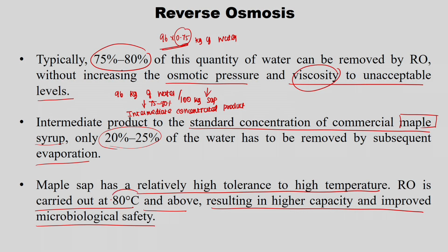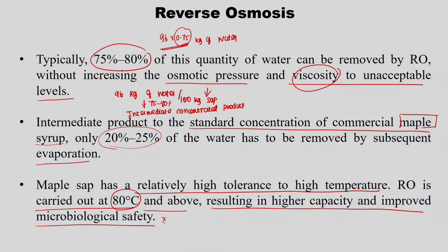And one must also be careful, because the membrane separation process we are doing is only twofold. One is to reduce the energy consumption, and if my food has large particulate solids, then how to handle that. So, for that purpose also we move to membrane separation. The other advantage is, since we are not using a high temperature process, my volatile aromas get retained, right, and also the nutritional quality.